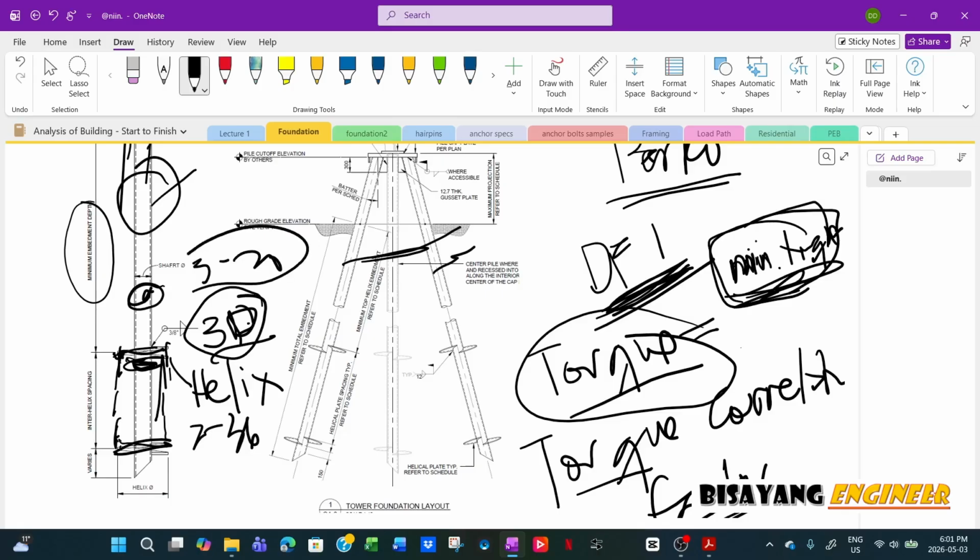You have the freedom to choose whatever you want. The only thing with piling contractors is that sometimes they have piles in their inventory, and instead of using the one I designed in the drawing, they will offer an alternative, use whatever they have in inventory, and provide the stamped drawing with all the capacities, and that is fine.